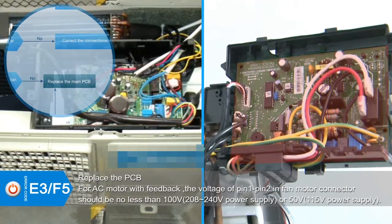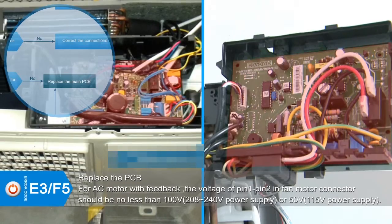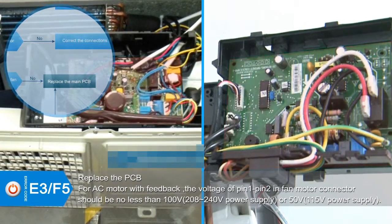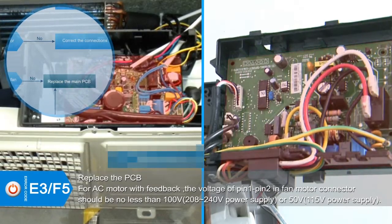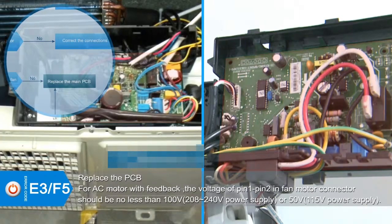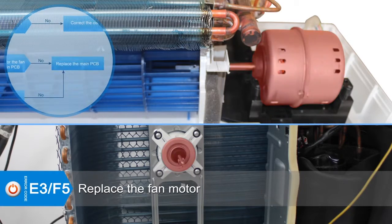If the value of the voltage is lower than 100 volts for 208 to 240 volts power supply, or 50 volts for 115 volts power supply, the PCB must have problems and needs to be replaced. If the value of the voltage is normal, the fan motor needs to be replaced. If the error still exists, replace the main PCB.